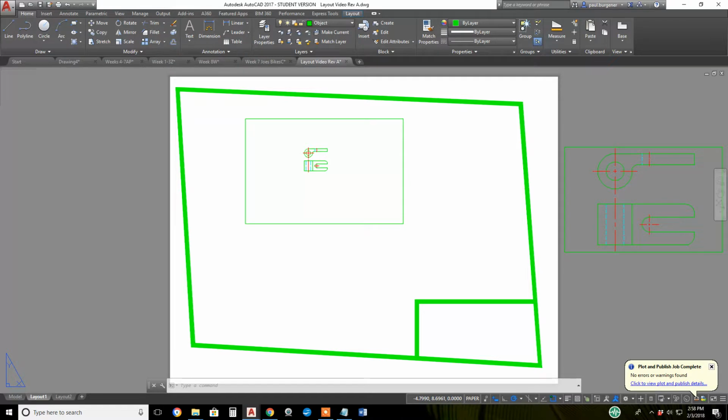Again, you can draw lines, arcs, and circles in paper space all you want, just like spray painting on the door through which you can see through a window into your model space. What's close to the edge is not going to plot out of the paper, though. As soon as we start to plot, you'll see a dotted line around the perimeter, and that's the plottable area of the paper. But for some reason, I think I'm set at a PDF file, maybe.